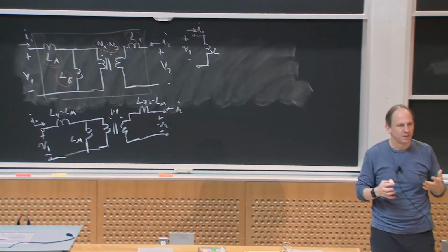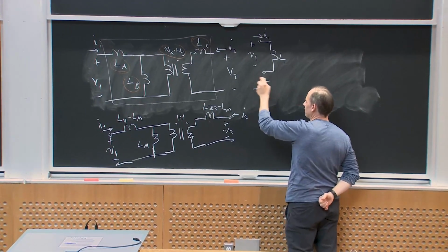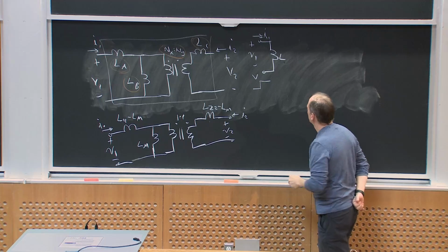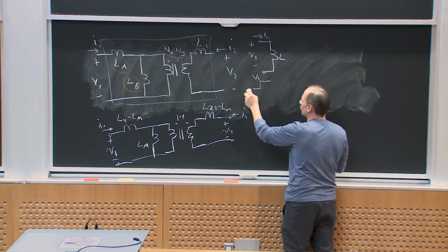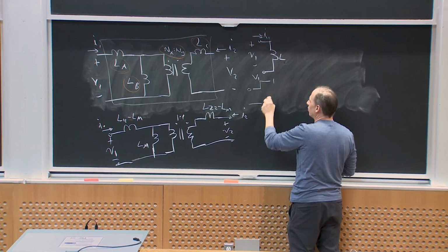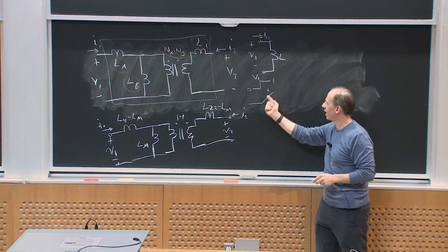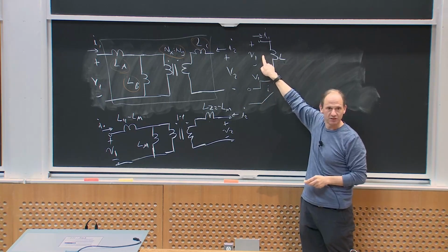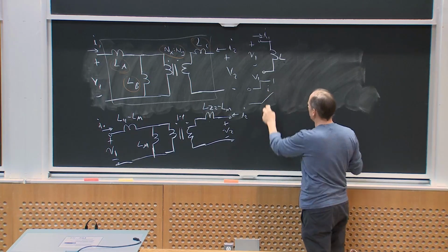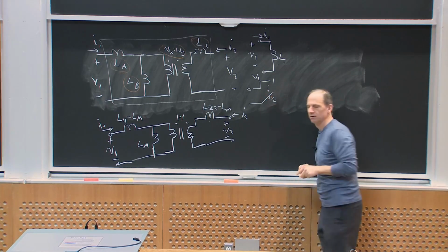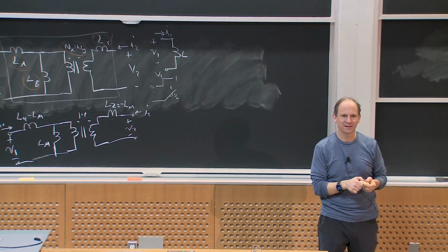Why is that? Because if I apply a positive voltage, right, so suppose I applied a step in voltage, here's V, right? Or here's V1. What should I1 do? Well, when I step the voltage from 0 to 1, I1 should go from 0 and ramp up, right? And since V is positive and I is positive, I've got energy going into this device, right? And this slope, di/dt, is 1 over L, right? What would happen if the inductance was negative?